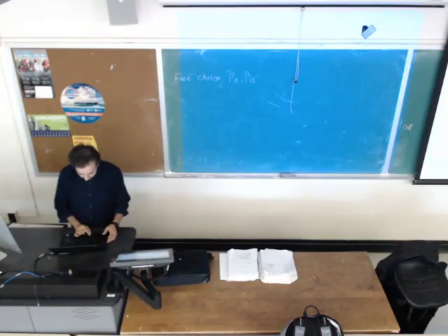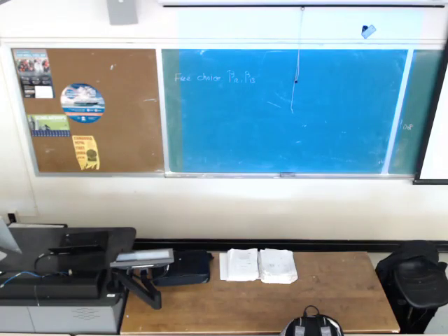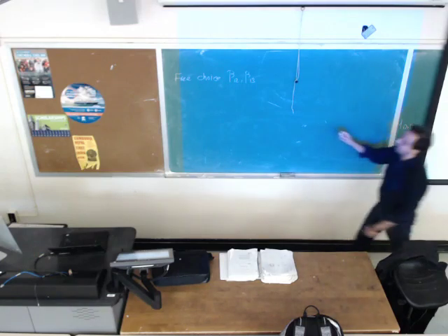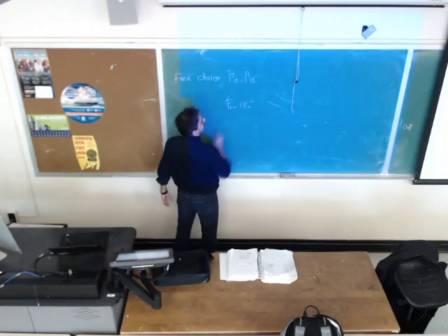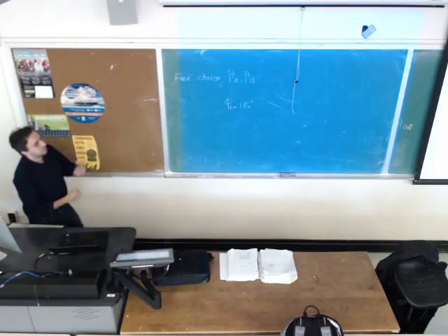But in some problems like this ladder, we would like to design a 4-bar mechanism. Ground, link number 2, link number 3, and link number 4. We would like to design this such that when theta 1, 2 is this angle, phi 1, 2 is this angle, and when theta 1, 3 is this angle, phi 1, 3 is this angle. And also we would like to have Phi1 equals 180 degrees at the starting point. This is the constraint on the problem. So if we want to get this, we should play with beta 1, 2 and beta 1, 3, try different numbers to get 180 degrees, which is difficult to catch.